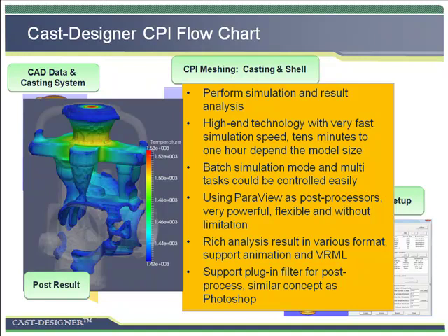The post-process of Cast-Designer is very powerful and user-friendly. Our development is based on the ParaView platform, so Cast-Designer can handle very big models, and also uses plug-in filter technology in post-process. Like most post-processors, Cast-Designer can provide rich analysis results in various formats, such as contour, deformation, vector and curves. We also support animation and VRML export for data exchange.